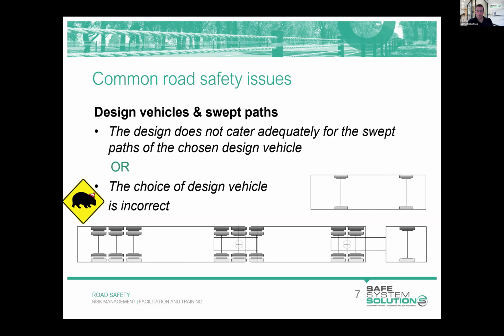There are a number of standard design vehicles that we use that are considered representative of different types or classes of vehicles, and it will depend on the environment that your road is in as to which is appropriate. We're talking about detailed design stage audits, but most detailed design projects are upgrades to existing roads, so you can get out there on site and observe the types of vehicles that are getting around and form an opinion on what types of vehicles the road should be designed for.